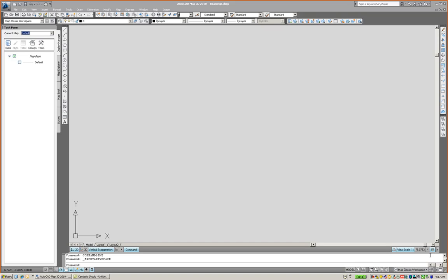The survey planes generally fly a long distance in one direction collecting data, then fly back collecting data along a parallel path. This process is often repeated multiple times, so you may need to combine these swaths and filter them by location to get the point cloud data relevant for your map.